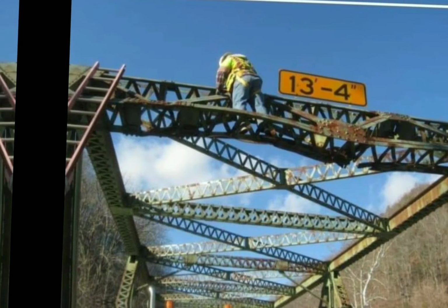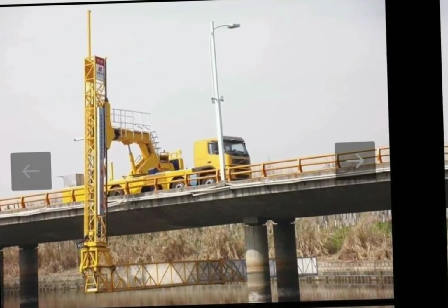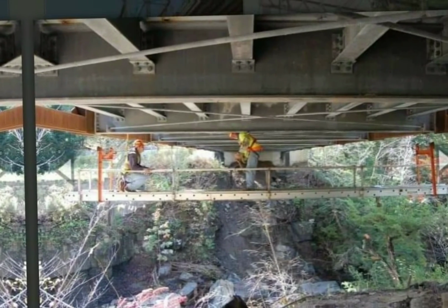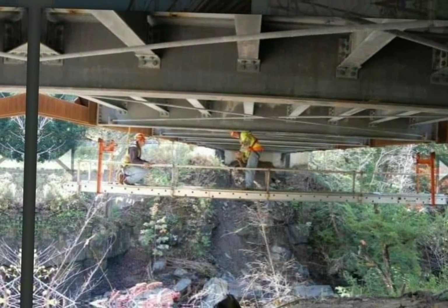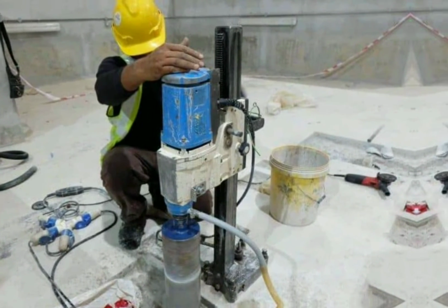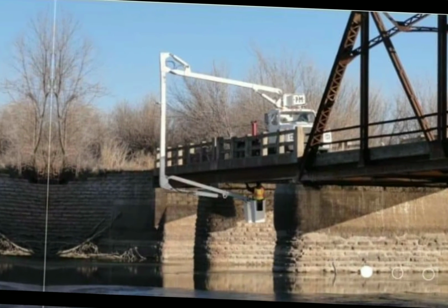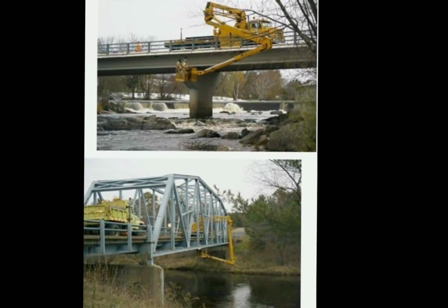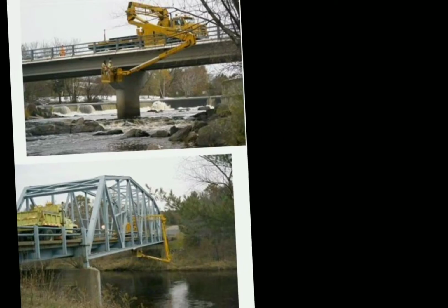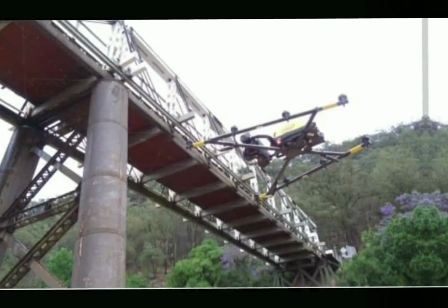Acoustic emission technique. It is non-destructive testing that detects and monitors the release of ultrasonic stress waves from localized sources where material deforms under stress. How does it work? It works by mounting a small sensor onto a component under test. The sensor converts the stress wave into electrical signals which are relayed to an acquisition PC for processing.